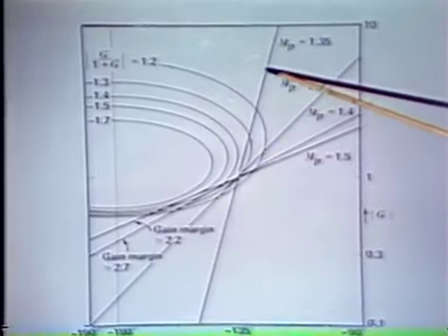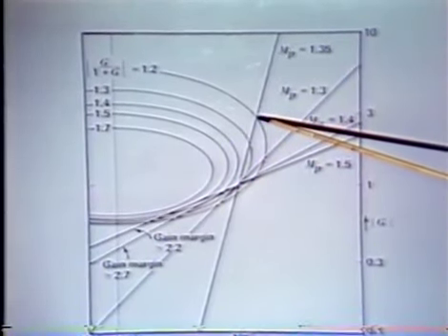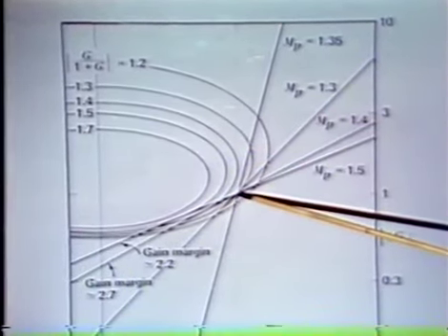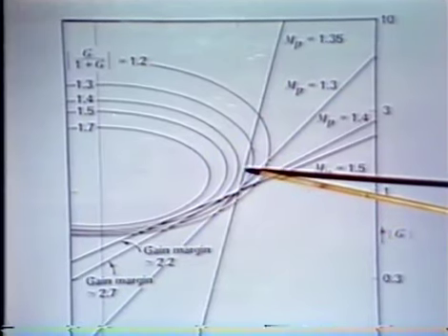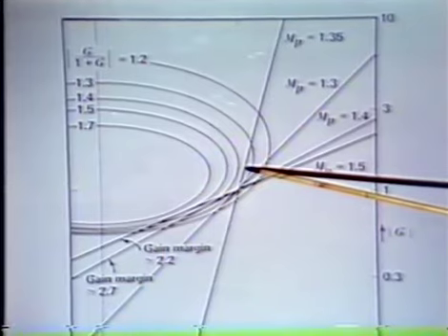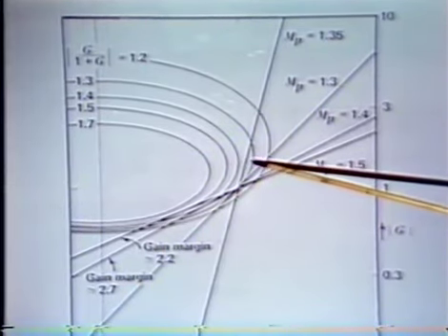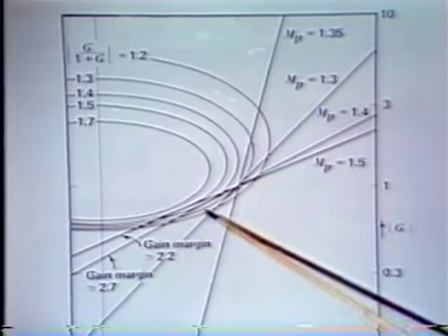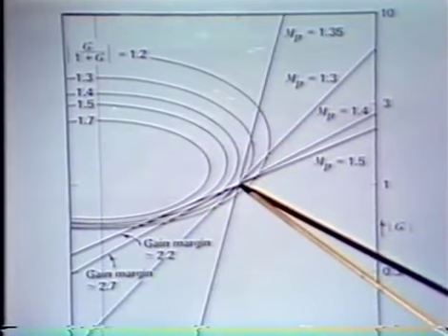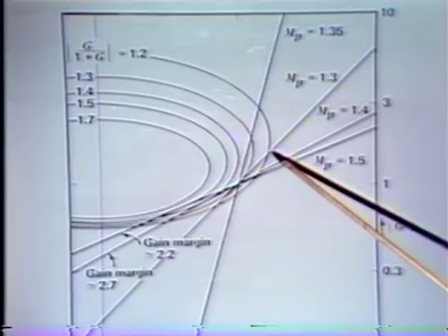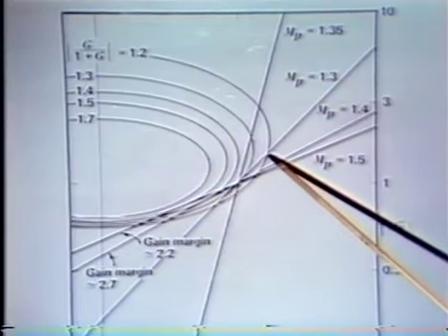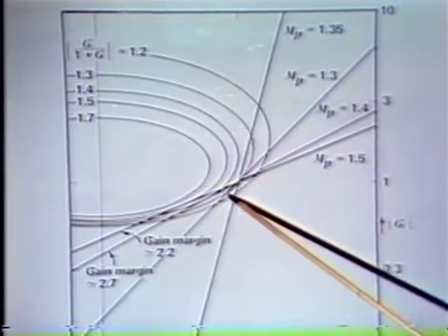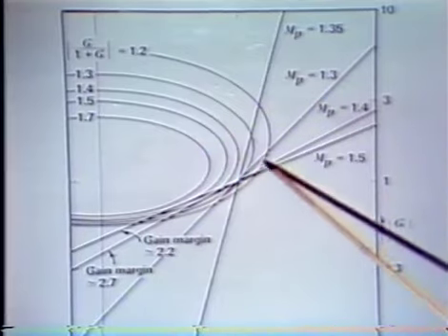And if, for example, we look at this curve, here we're up to a closed loop magnitude of 1.2. Here we're up to a closed loop magnitude of 1.3. And we get to our MP, our maximum value for the closed loop magnitude, somewhere between the 1.4 and the 1.3 curve, maybe 1.35. We have a little greater slope, like so, for our assumed AF product, again with a phase margin of 45 degrees. Why? Let's see, here we have a closed loop response, a magnitude of 1.2.